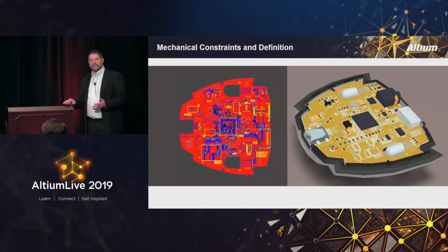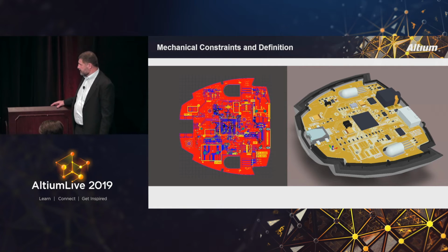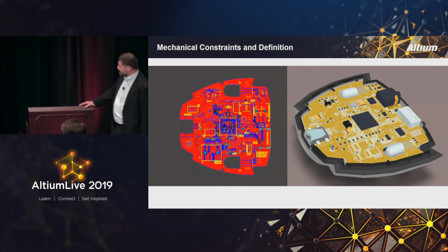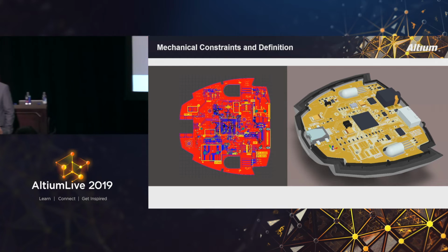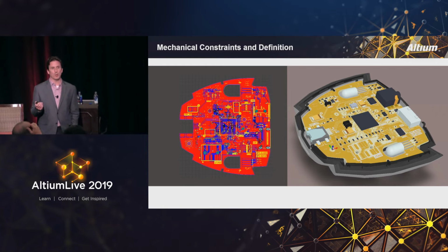And oftentimes things will get changed midstream, so just beware of the landmines that come with that. Make sure that everything's going to match up for what your pinouts are. Huge mistake, and it's a real big gotcha because it's going to come at the end when you find it usually. So one thing I would say is, in this, you should be deciding exactly where your connectors are going. And here's a quick tip I'll give you.